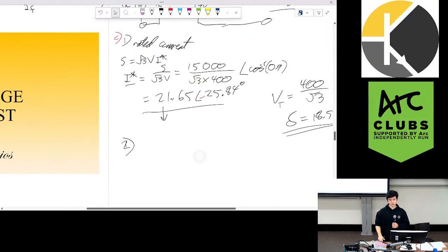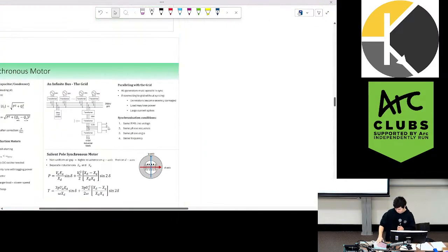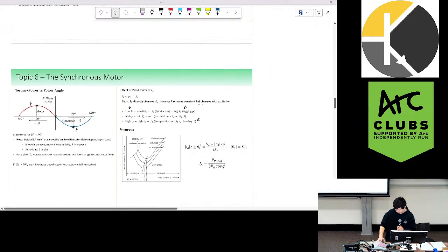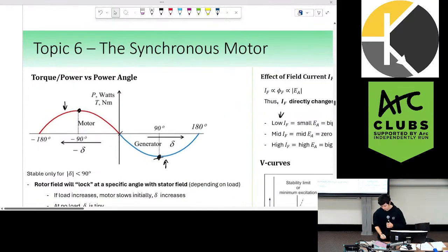All right. So as we mentioned previously, if we're clocking a little bit past that 90 degrees, as we saw in the torque delta graph, if a system needs more than this torque, well, afraid to say that the synchronous machine cannot supply it. It can't supply it, so what does it do? It falls back down to zero. Torque falls. Spins out.